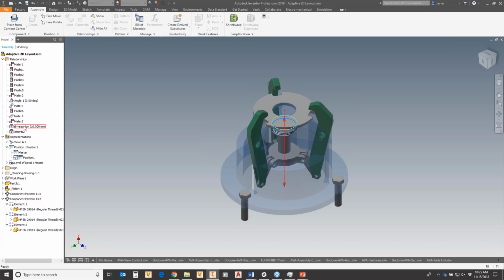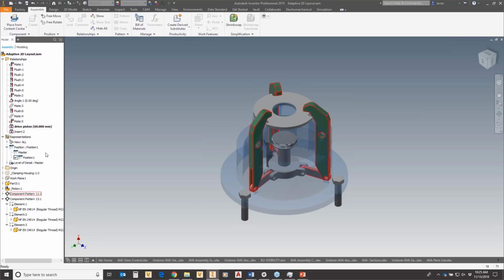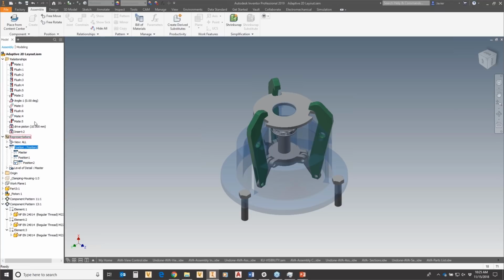If I right-click, I get options I don't normally see. I see override, I see modify override, I see suppress override, and in this case, I just want to modify the number that's there and change that to 60. Okay, and that creates just an alternate position, position 1. I'll right-click on this again and create another one. It always starts off back to the default, and this position might be maybe a halfway point, if you will.